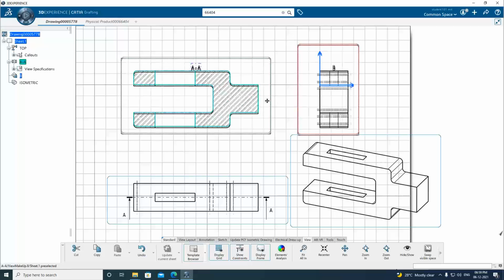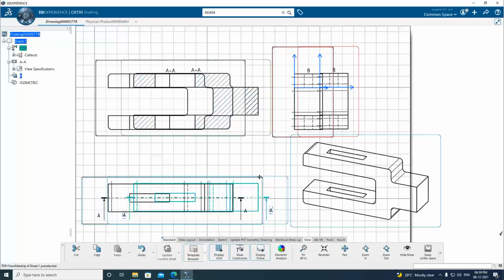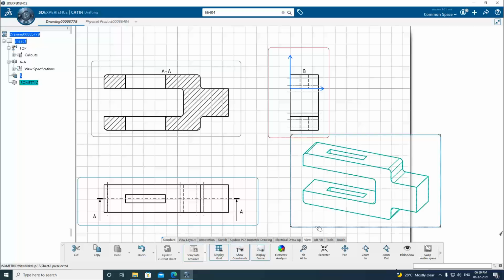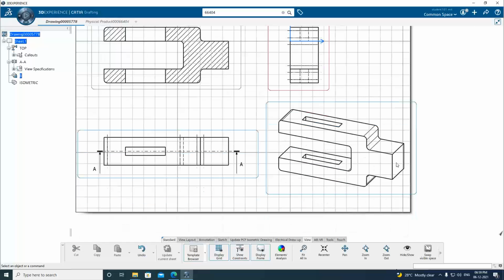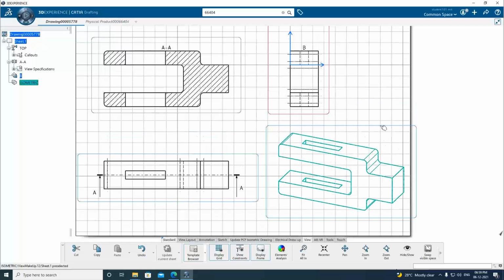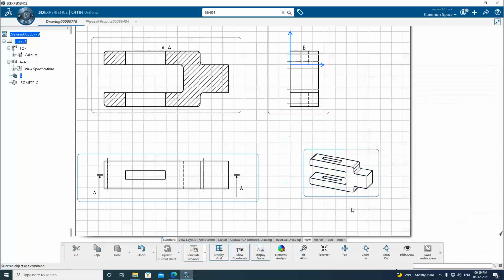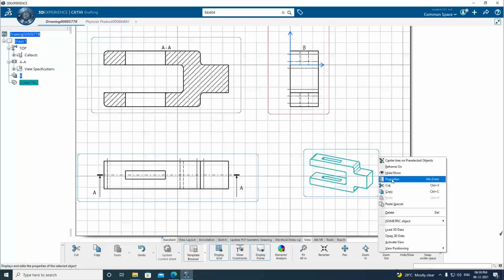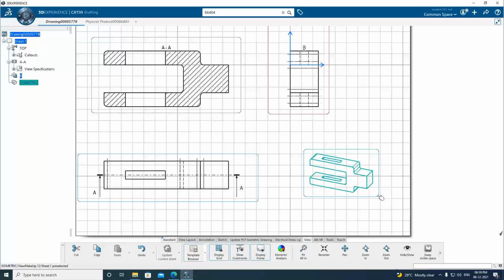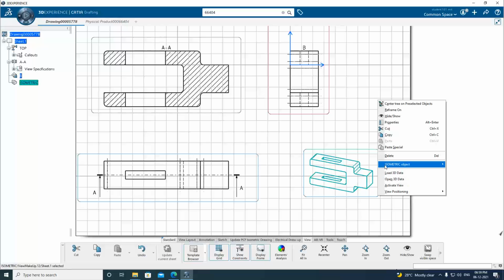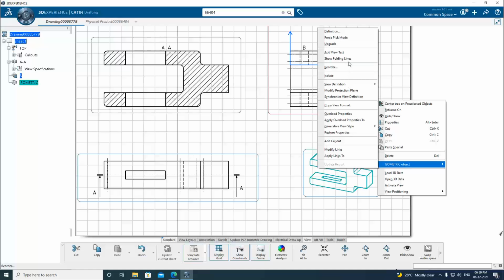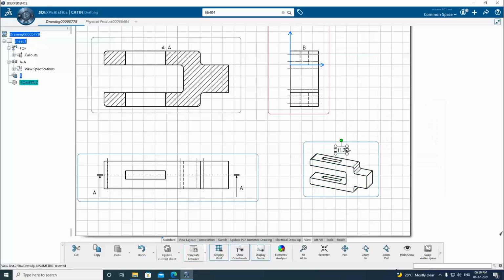If you want to move the views on the sides, just move it this little bit and you can fit it. So like this. So suppose if you want to say this, I want it to be in 1:2 ratio, apply, you say, click on OK. Even you can give details like it is scale has been reduced to 1:2. Otherwise people may not come to know. So what you do is go to isometric, here add view text. So view text you can do.